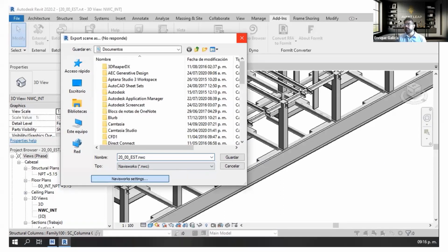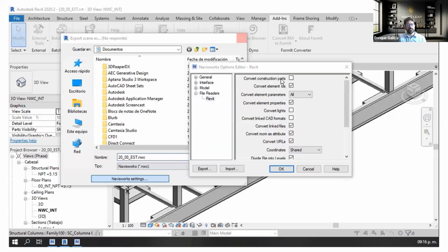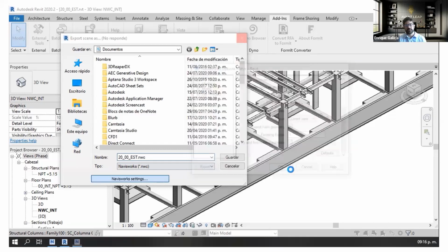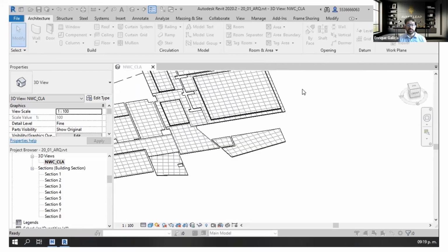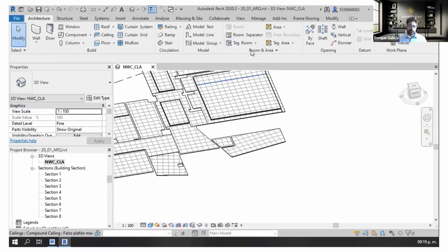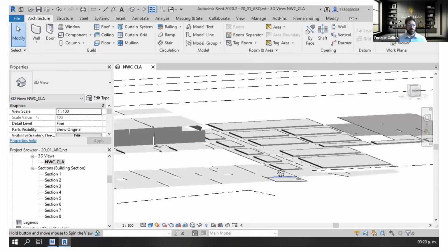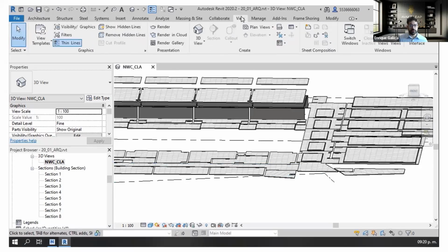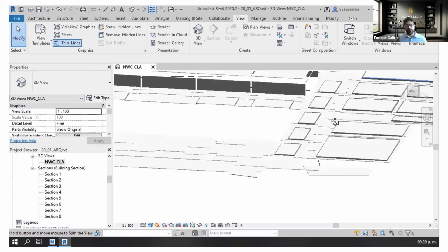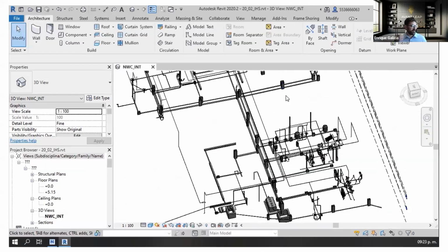That way we know that we are not doing clash detection on just any object, but only on the relevant ones, such as structural elements, MEP connectors, MEP types of objects. As well, if the walls are pre-assembled or separately cast, they need to be taken care of, because otherwise elements can have issues. If we're analyzing ceilings, types of floors, or rooms, those might come into consideration, because we need to properly export it in order to review it, right?